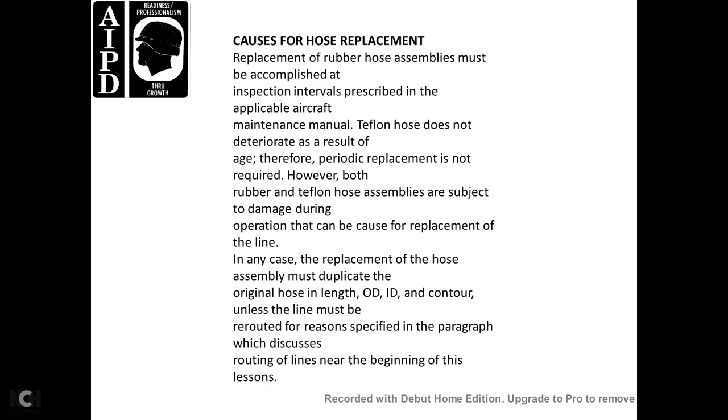Replacement of the hose assembly must duplicate the original hose in length, outside diameter, inside diameter, and contour, unless the line must be rerouted for the reasons specified in the paragraph which discusses the routing of lines near the beginning of the lesson.